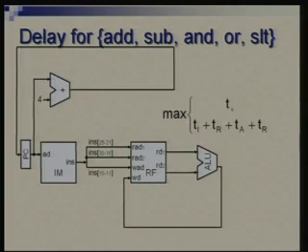So I can afford to have a slower adder here because that's going to cost me less. Therefore T plus could be much larger than TA. You would recall that the delay in carry look-ahead addition and the delay in carry propagate addition could differ quite vastly. One is proportional to n, the other is proportional to log n, so the difference could be large.